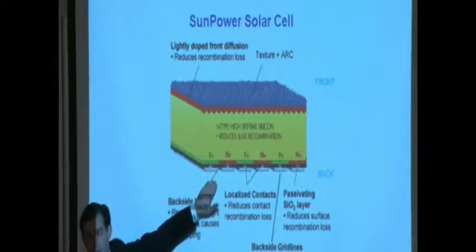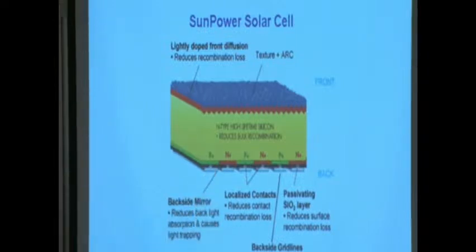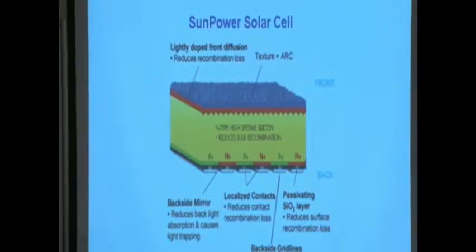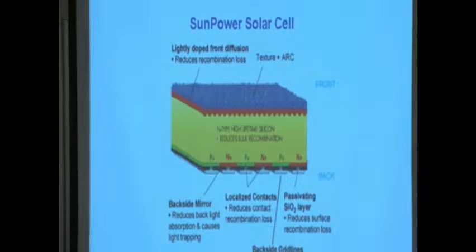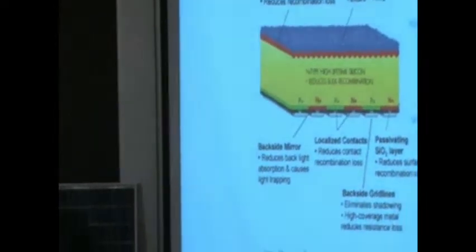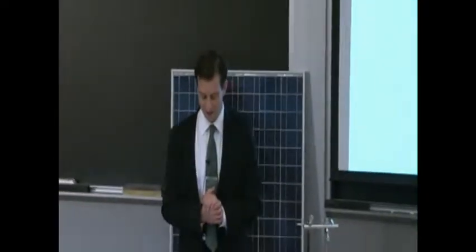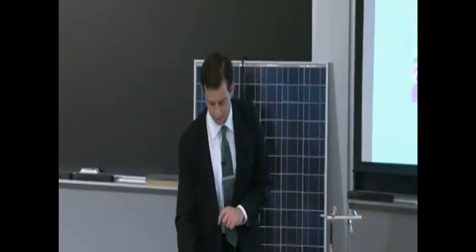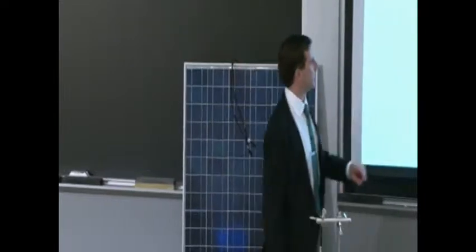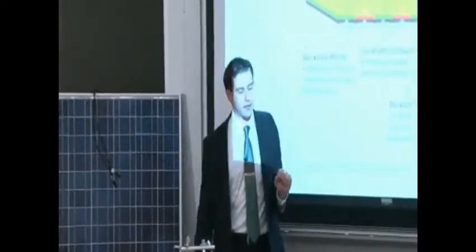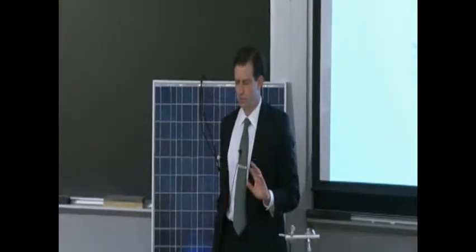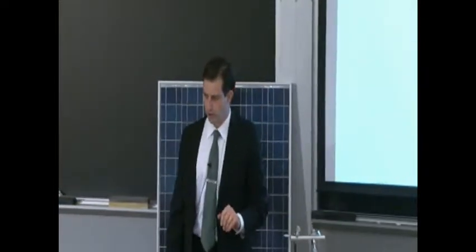Where you have your metal, you're going to be absorbing the light, or you have a higher probability of absorbing the light than you would if you had a dielectric semiconductor interface. So the device design can get pretty complicated for these super high efficiency devices. And they're worried quite a bit about light trapping, other things as well. How efficient has that one been? This one right here, in the lab, 24.2%. In commercial production, 22% and change, 22.4, I think.